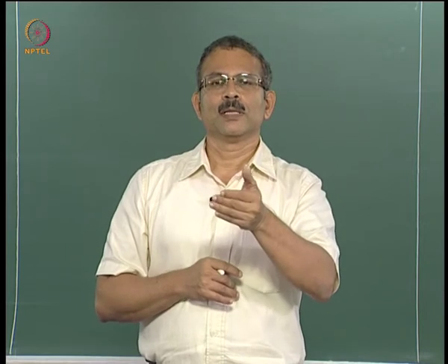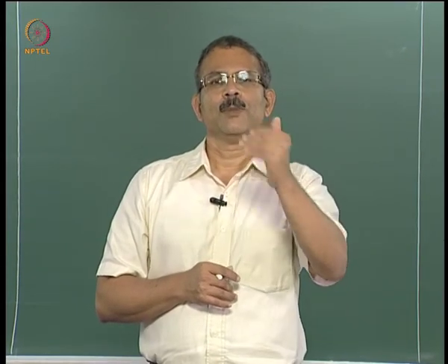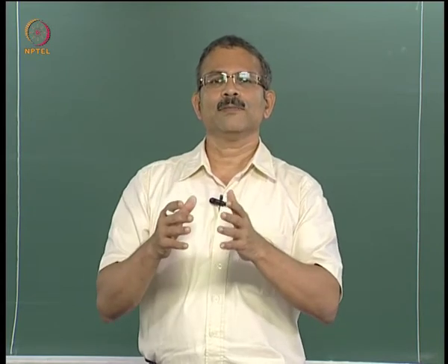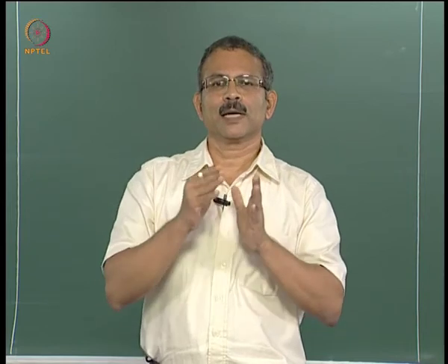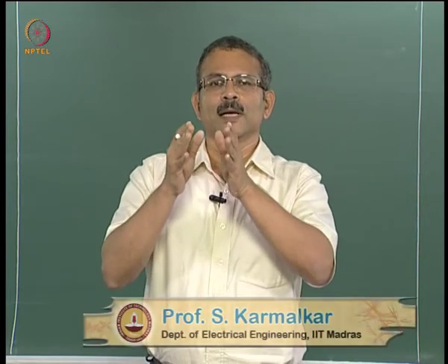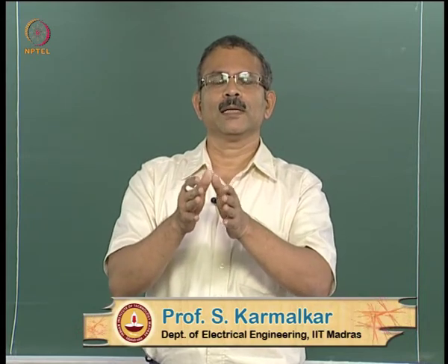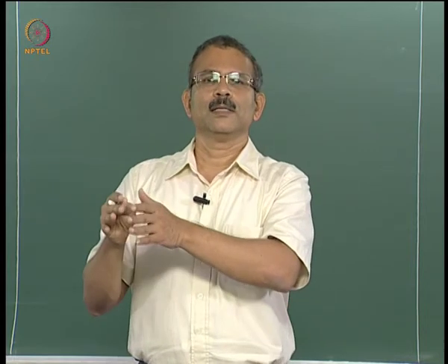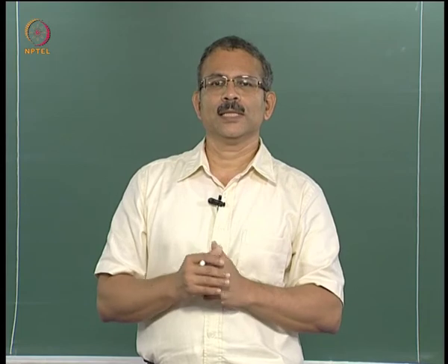And we showed that you need to do a number of approximations of the momentum balance equation to achieve this simple relation for current density, in which the current density is shown as a sum of three components: one due to concentration gradient, one due to carrier temperature gradient, and the other due to electric field. We will continue the discussion in the next lecture.